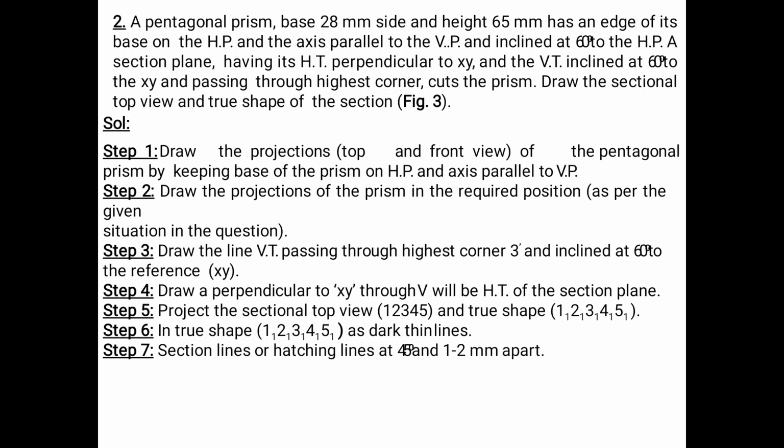So there is one more problem, another model, which is a pentagonal prism, base 28 mm and height 65 mm, resting on its base on the HP, and the axis parallel to the VP, inclined at 60 degrees to the HP. A section plane having horizontal trace perpendicular to XY and vertical trace inclined at 60 degrees to the reference line, passing through the highest corner, cuts the prism. Draw the sectional top view and true shape of the section.